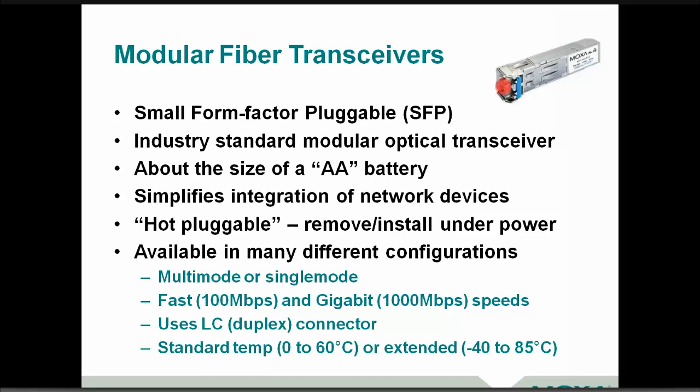This is a really great technology. It's also hot pluggable, so you can remove and install this under power. And the really key part of this technology is the ability to have it available in different types of configurations. So here's where you customize it for your application, multi-mode or single mode, 100 meg or gigabit, and also another thing to think about, standard temp versus extended temp.